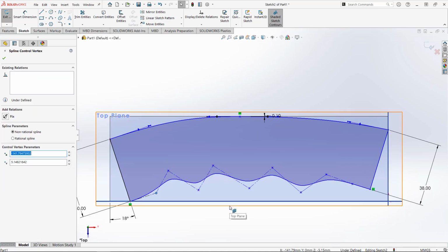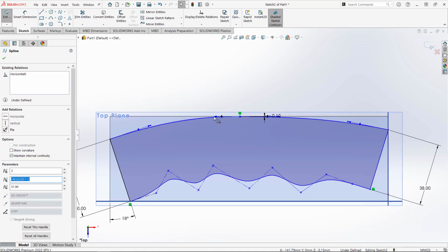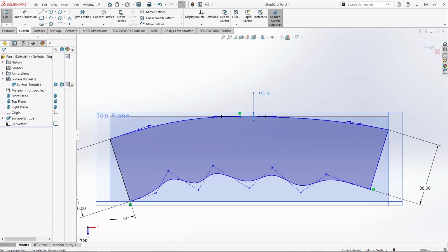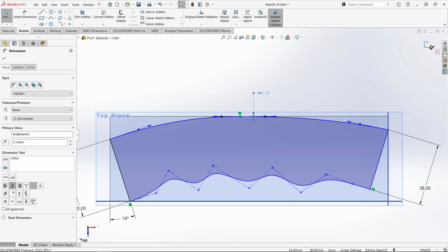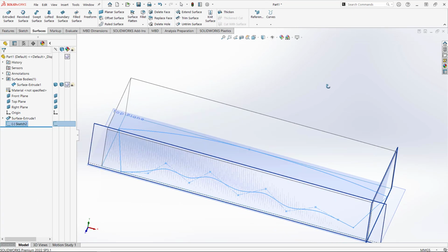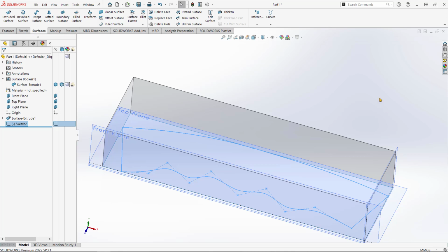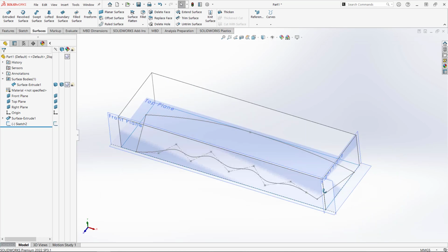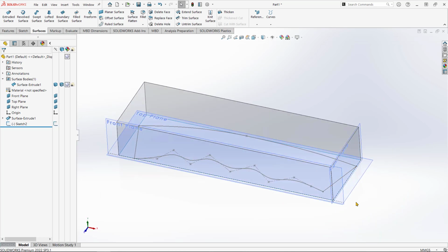So that looks okay. We want a general kind of curve to this handle, and then, as I say, we want these indent shapes for our finger points. So then I'm going to accept this sketch. So click on the button to accept the sketch. Now I'm going to click off the sketch to deselect it so that I can see its true colour, which is this kind of grey colour, the same as all sketches.